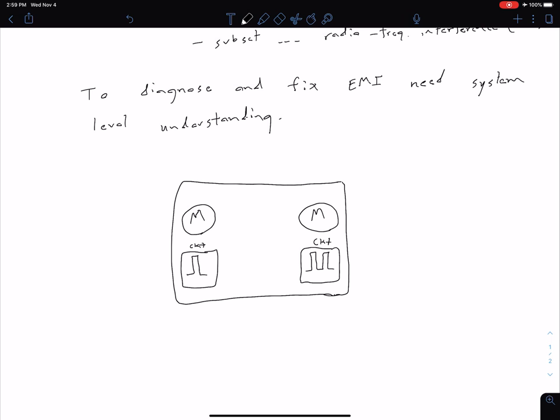They put the software into their robot, and as soon as they tried to test it with the robot, the software wasn't working at all. It turns out that as these motors are turning, they have commutators which are connected to the coils, and the brushes of the motor are connecting and disconnecting from the commutator as the rotor is spinning around. Don't worry about that too much if none of that made sense, but the main point is that there were EMI pulses, or rather EM pulses, that were interfering with this circuit.